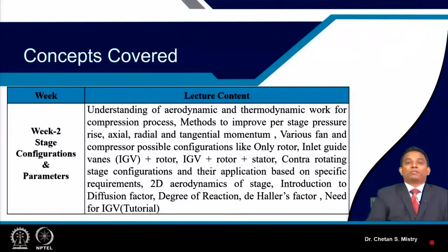In order to estimate the diffusion for per stage or for all your stages during your calculation, you need to do the calculation for diffusion factor. This diffusion factor also helps us count the number of blades. How many blades you will be using can also be estimated if you assume your diffusion factor to be some number. And we have seen that number, as per the recommendation, is a maximum of 0.5.